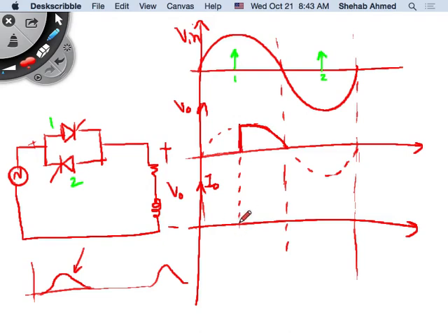So I have a current that's going to ramp up, and it will not fall here, because this is where the resistive load current will become 0. It will fall somewhere beyond. Somewhere beyond will be the extinction angle. Exact same theory, actually exact same equation for current. Does not change. I of t will be composed of a natural response and a forced response. The natural response is A e to the minus t over tau. The forced response is the voltage divided by the impedance, Vmax sine omega t divided by the impedance. And so you'll end up with exactly the same equation as before.